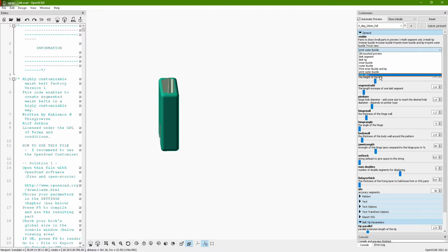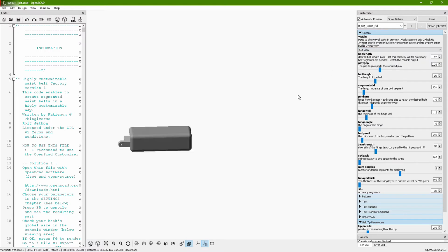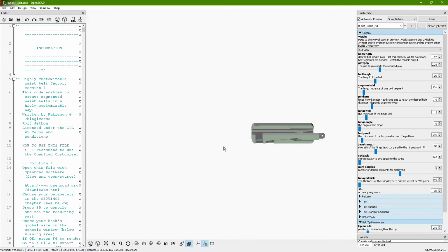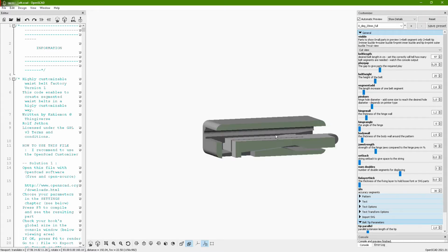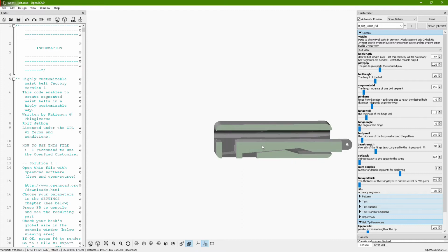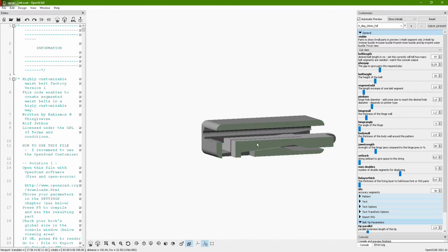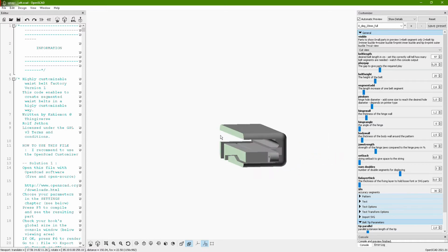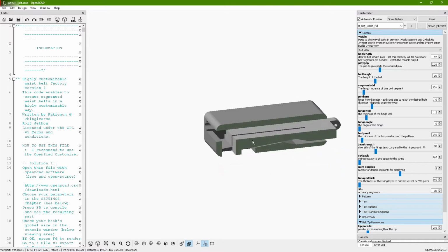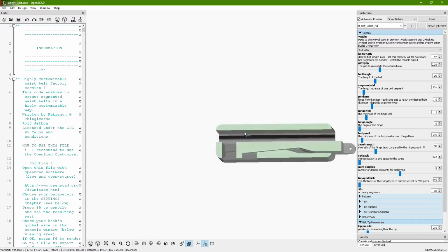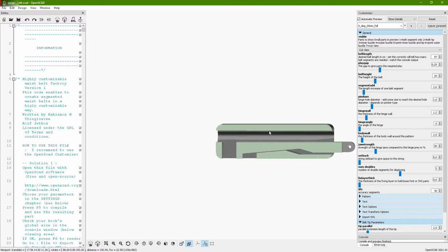The next one is the cut preview. That's sometimes helpful if you want to see if your buckle and the squeezing inside the buckle may function correctly later. Usually it does if you select the correct angle, but you have the possibility to change it, so you can double check inside your cut preview if this is still going to function.